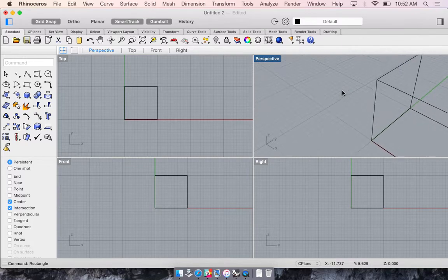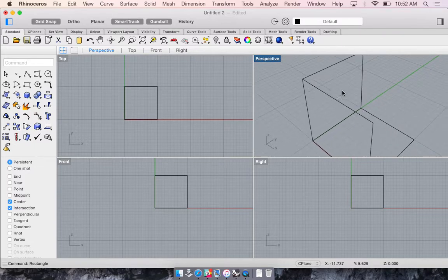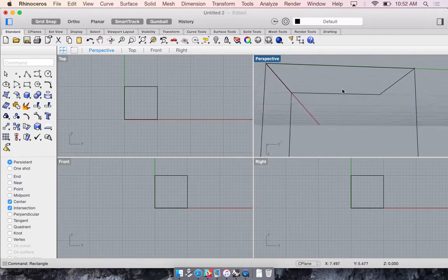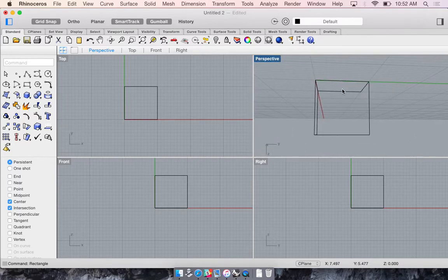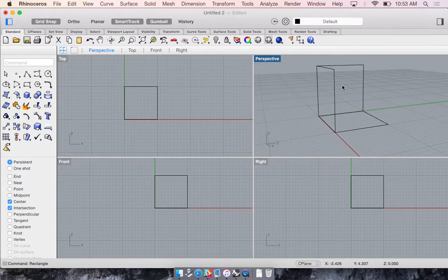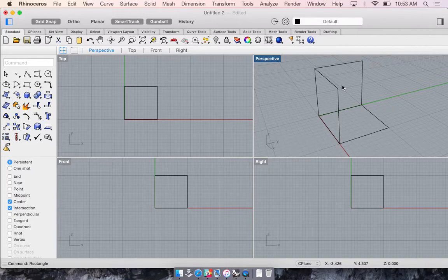Okay. And now what if you get something like this where the thing you're looking at is kind of out of your screen? You need to move it back in. That's called the pan. That's where you hold Shift and then two fingers move it back over. So very quickly I can get a view that's weird, kind of out of the way, and I can zoom back out, I can rotate it back around, and then I can kind of pan it to where I want it to be. That'll take some practice.